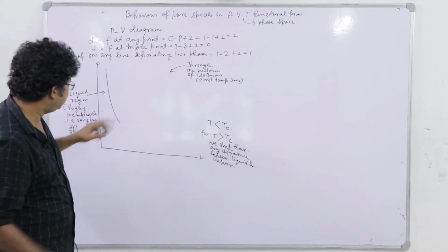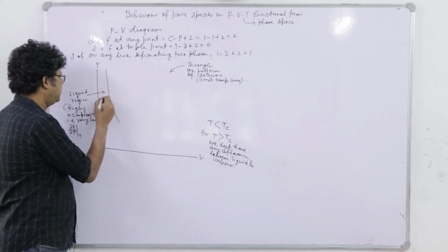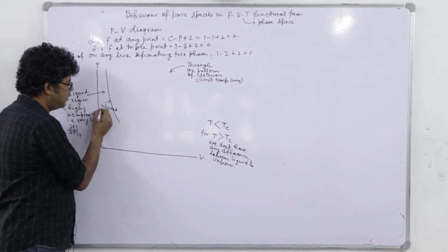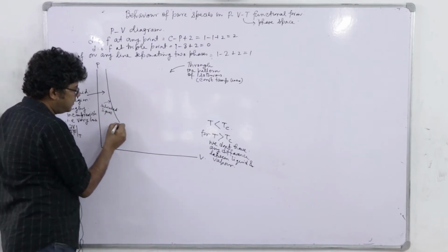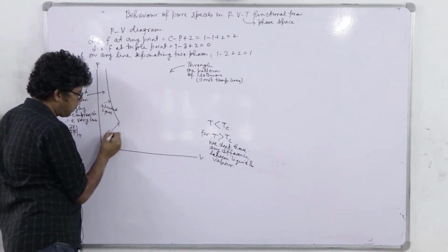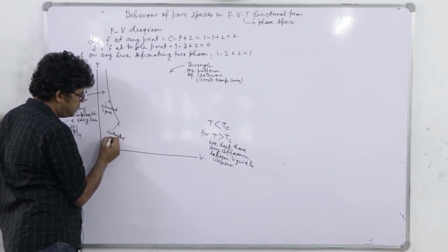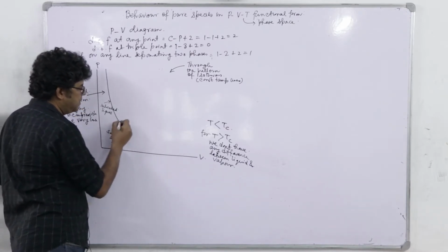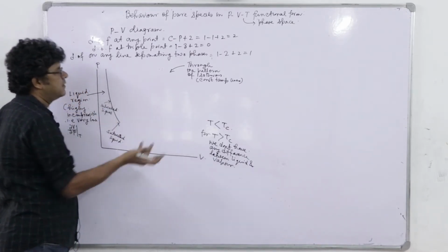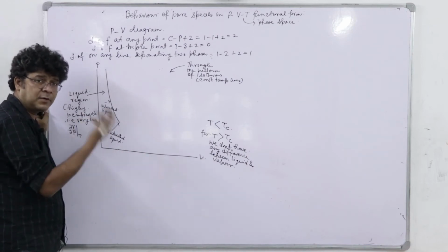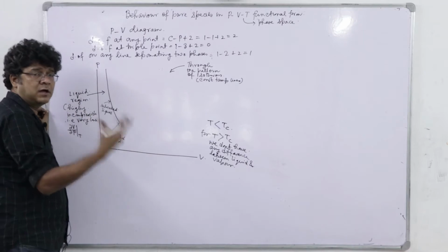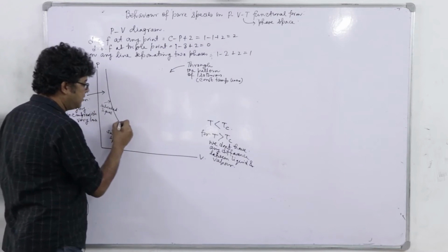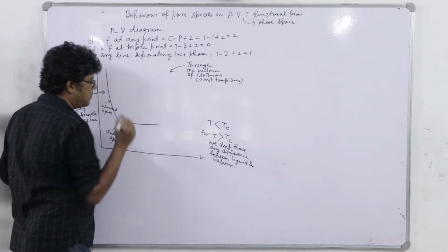Because from here, this is the subcooled liquid region, at this point it is saturated liquid, and now further if you try to reduce the pressure, it will not change unless it is fully vaporized and transforming itself into a saturated vapor, moving through a two-phase region, right. So, that represents the phase change. So, it will be like this.